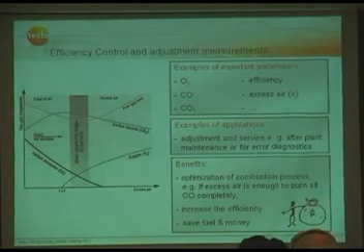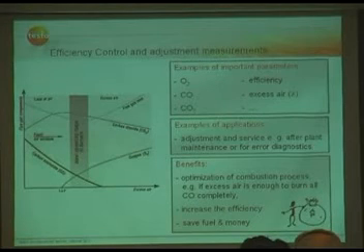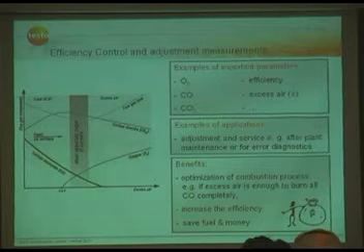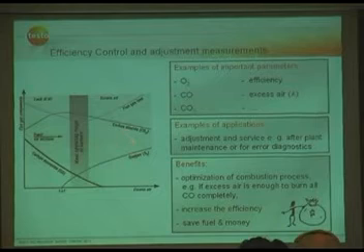And with regard to the CO2 max value, each flue gas analyzer has a specific list of different fuels with specific parameters behind, like the CO2 value, and therefore you don't have to worry about the CO2 values if you're using different fuels to correct the right lambda or the flue gas loss.